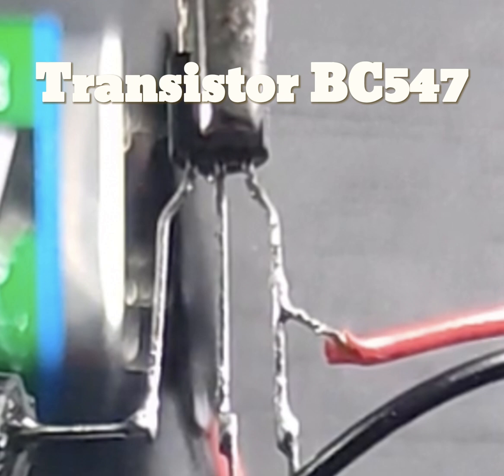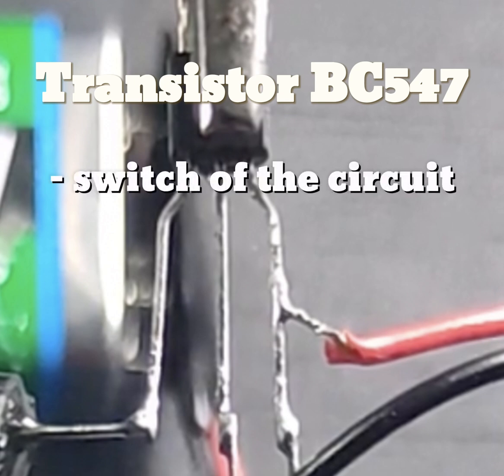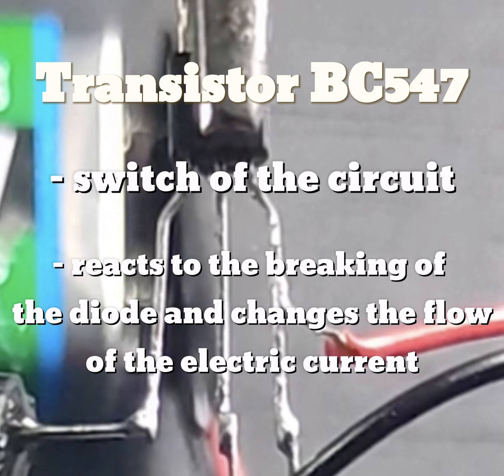The transistor BC547 is basically the switch of the entire circuit, as when the diode breaks due to the heat, electric current flows to the base of the transistor, opening the path between the collector and emitter, allowing current to flow to the buzzer, thus creating the buzzing sound that will be heard.